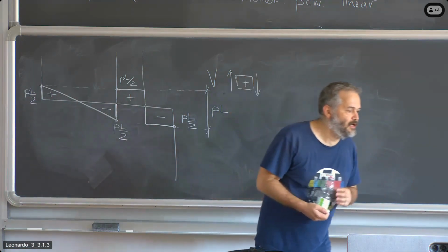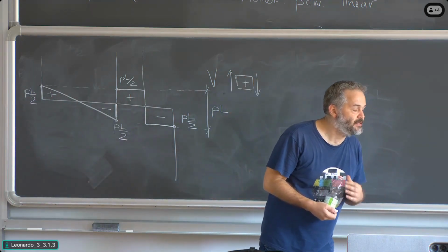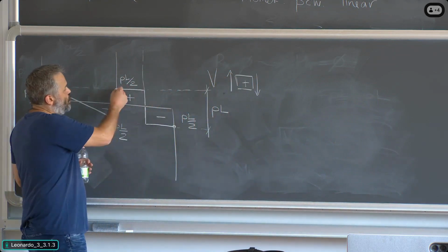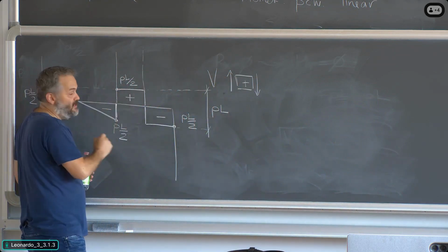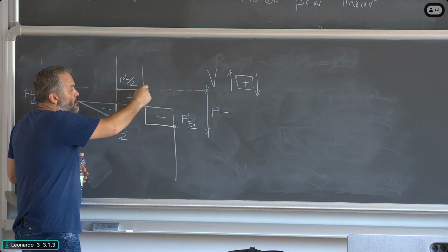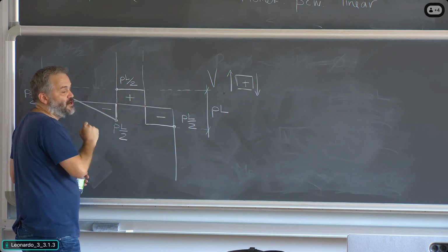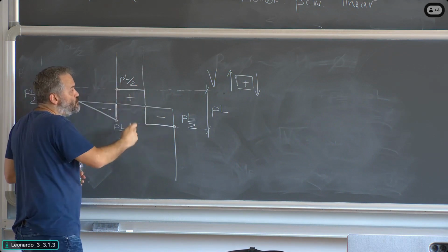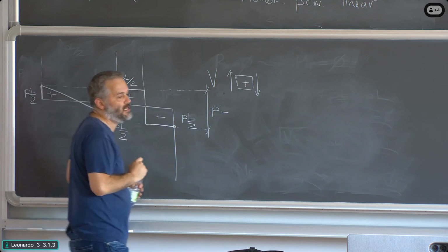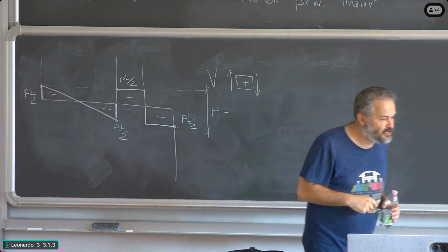Now, for a person who asked in the chat, can you see what piecewise constant means? Constant in the first half span, constant in the second half span. So both portions are constant, but with different values. One is positive, the other is negative, and therefore there is a jump at mid-span where the concentrated load is applied.